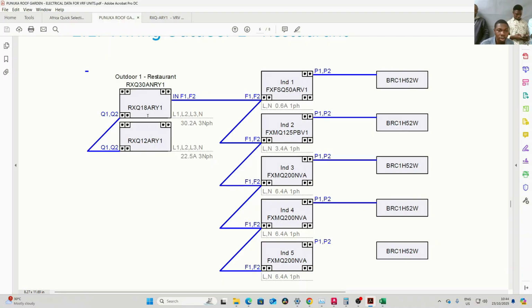What is our V, the voltage? Three-phase voltage. It's 400 now. They've standardized it to 400. What's our single-phase voltage? 220. Okay, so what is our cos theta? What's the name we call cos theta? The power factor. So let's multiply it. Let's just say 16.7 kilowatts.